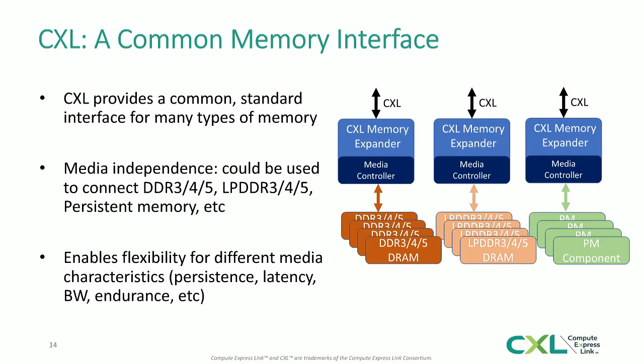The benefit here is that now that you have a media-specific controller, you can address some of the specific challenges of those media types directly. So now you can have a specific controller for each type. If there are asymmetric timings or non-deterministic timings, media-specific error handling mechanisms, or other needs that a particular type of memory requires, you can do that with these media-specific controllers. But with CXL, on the system side of the interface, we now have this common standardized interoperable interface.